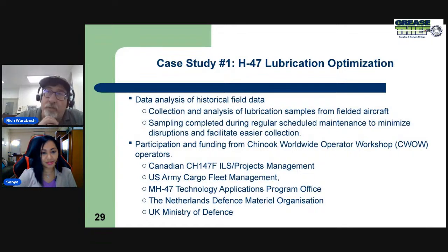And what you see is that when you have a new machine design, somebody has to come up with a starting point, somebody's best guess of what we should be doing with respect to grease. There typically isn't the data there that says what's optimal. And as time goes on, when I said earlier that we usually use about twice as much grease as we need to, it's a natural human thing, because if everything's fine, okay, no failures, what have you. But what happens the first time the grease doesn't look right? We have a failure. The grease looks kind of shot. Oh, grease more often. It's just a natural thing, until we default into the state of over lubrication.